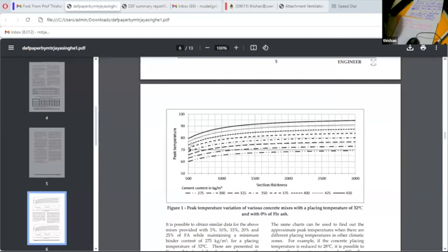But you can't go up to 1000 because there's a risk of DEF occurring, but generally it doesn't happen because columns are kept very dry. But you are risking the building because you don't have enough knowledge. So if you have knowledge, you look at it and decide, okay, I'm going to use some fly ash. Let's say you decide to go for 85% of 400. What is 85% of 400? 340 cement. Is that right? Yes. 60 fly ash, 340 cement.